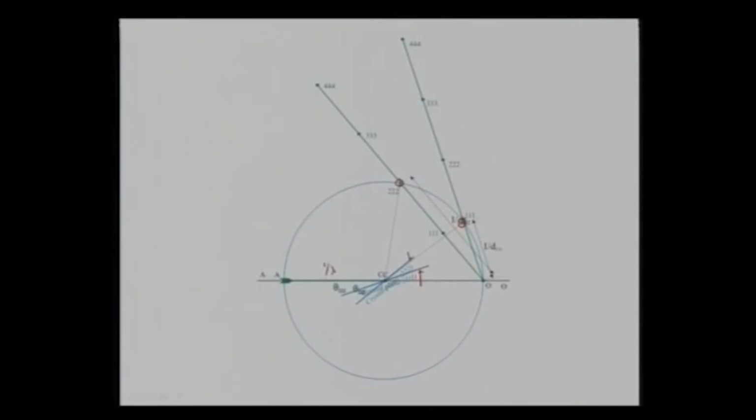And now I can see the plane 111 has to be aligned differently as compared to the plane D222 to give me a diffraction spot. So I need to have kind of a polycrystal material with a proper orientation with my plane 111 and plane 222 to produce a diffraction spot at a particular location in the Ewald sphere. So my reciprocal lattice has to be such that it basically comes out or touches the Ewald sphere, so I need to have a polycrystalline material. So my reciprocal lattice will be accordingly to a particular plane, and my Ewald sphere is constant because my lambda value is fixed for that. So I can get a diffraction spot at some location.